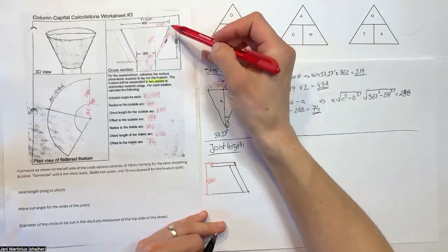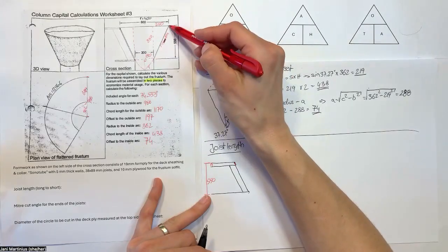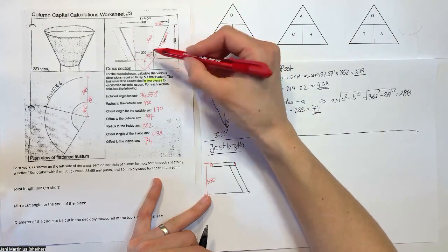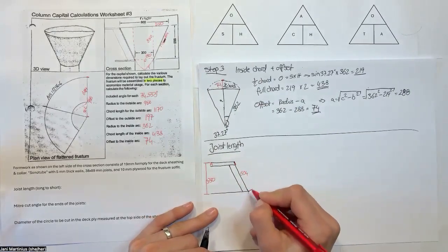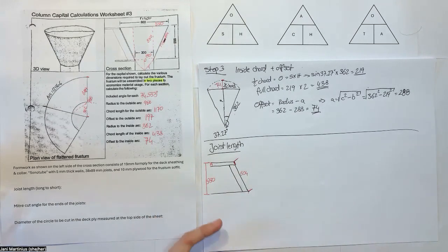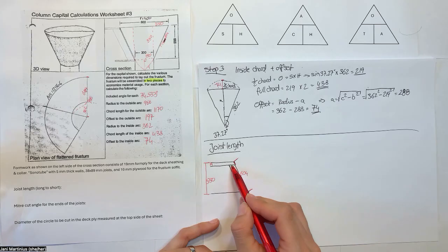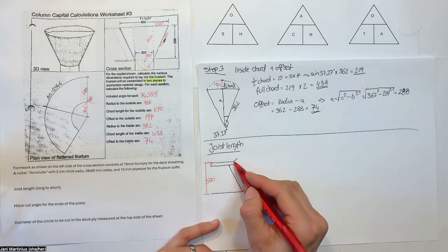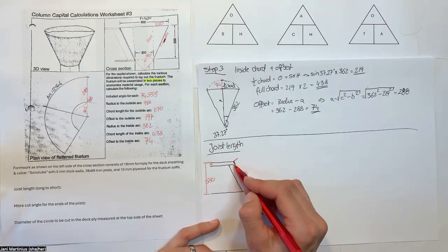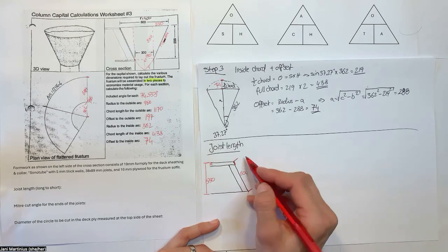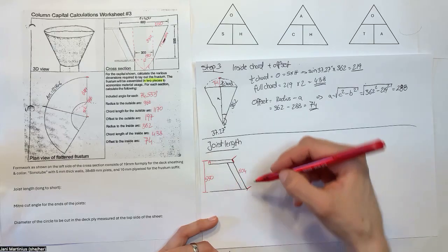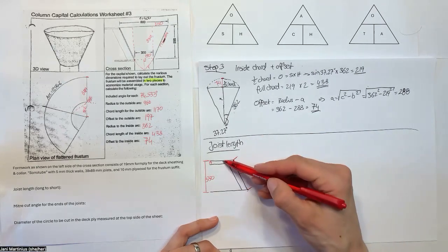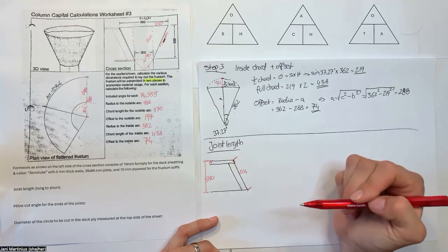If we look on the other side, this is the radius that we figured out before, the 604, and it goes from here to the top of the plywood. Now our joist fits in between, right? It fits underneath the plywood. So we have to take away from the 604 not really the diagonal, but the angled length of the plywood because it's on an angle. The whole measurement is here. If we only took off the 19, well, that doesn't quite work.